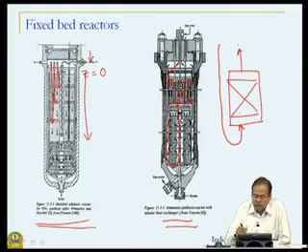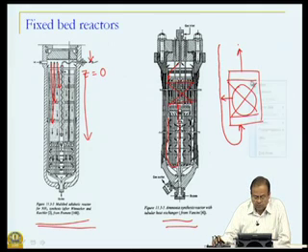So, in this portion the reaction takes place, energy is generated, that is transferred to the reactant which is flowing in the shell, so that the reactant gets preheated before it enters the reactor. So, this is the operation which we are going to see in today's session.